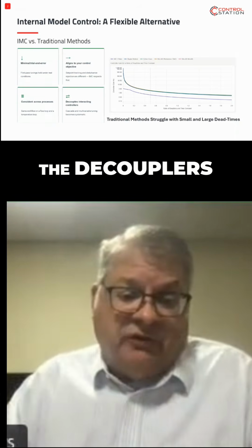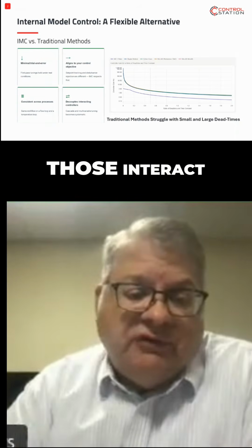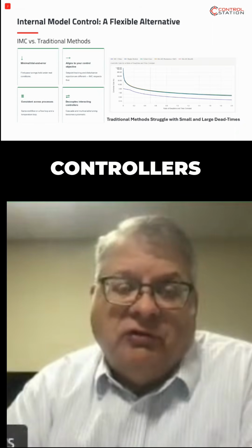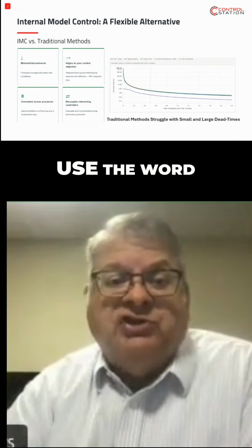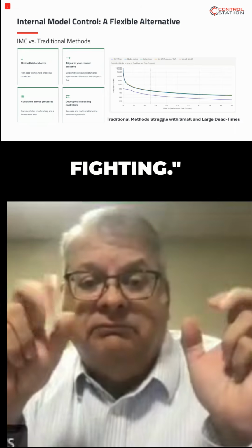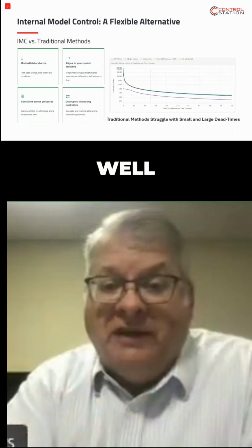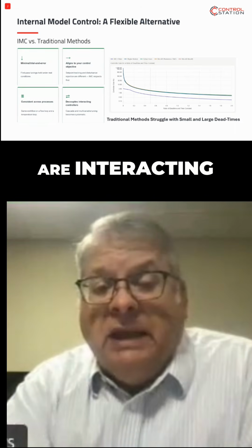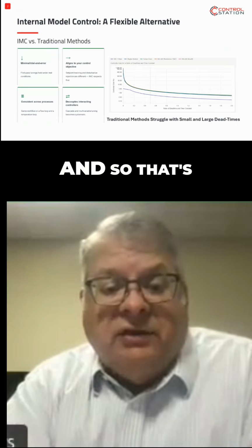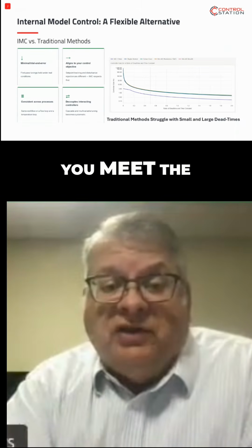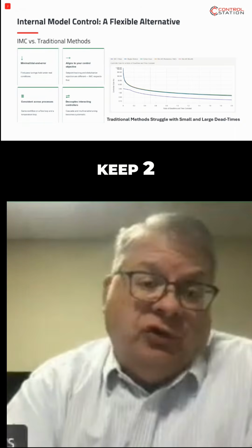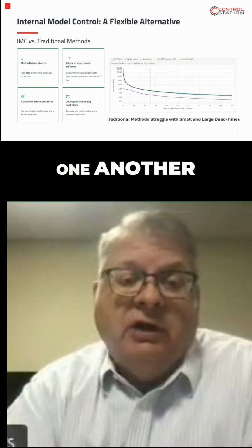And then we have the decouplers, right? The decouplers, those interact where we have controllers that are interacting with one another. You've heard the operator use the word, well, these two are fighting. Heard that in the control room? Well, that's probably because they are interacting. And there's a solution to that. And so that's why using IMC tuning correlations can help you meet the control objectives and keep two controllers that are fighting one another from doing so.